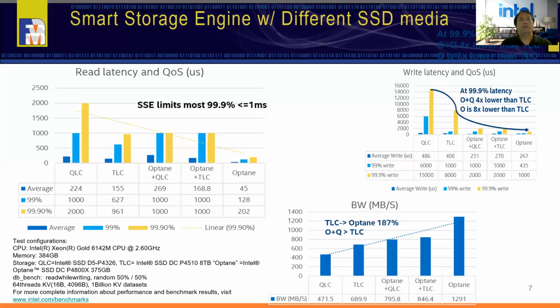So let's go back a little bit. When people see a drive with long tail read latency on a random read-write workload, typically the reason is that when garbage collection kicks in, your read latency, especially the tail latencies at 99, 99.9, 99.99, even 99.999, jumps higher, because the garbage collection prevents the firmware from giving back your data. We change that by sequentializing the data to the drive. There's no garbage collection, so your read latency is going to be pretty close to the read spec.